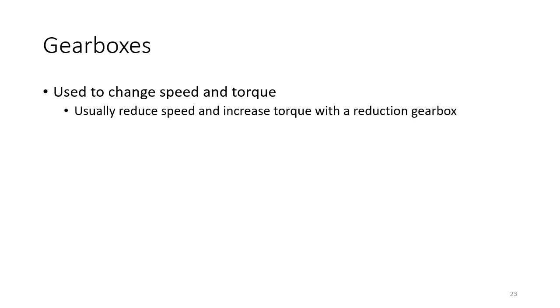The gearbox also adds a load in itself. There is some additional inertia and there is some additional friction inside the gearbox, but normally that's minimal compared to the overall final load.